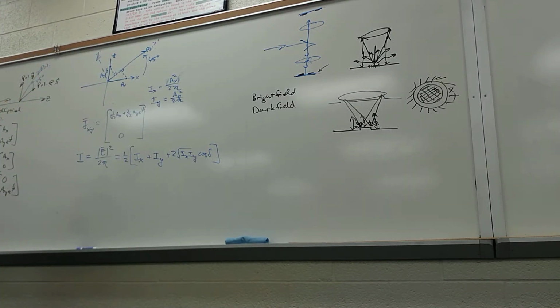Excuse me. When we set up the problem, you said that the polarizer is rotated 45 degrees to X, yes? Yes, we set a polarizer at 45 degrees to X, on purpose, because we want to force interference between the two orthogonal beams. So in your case, if you set up the antenna 45 degrees with respect to the ground plane, then you're going to force interference between the TE and the TM polarization in your system.